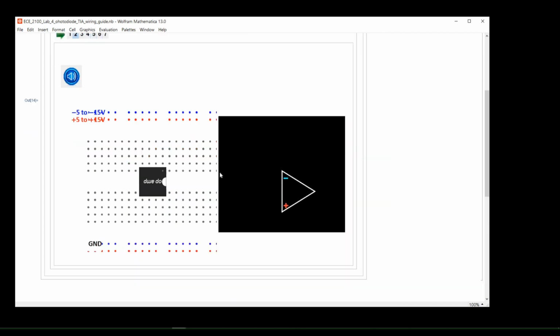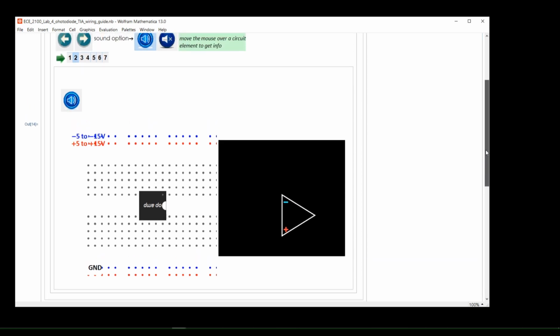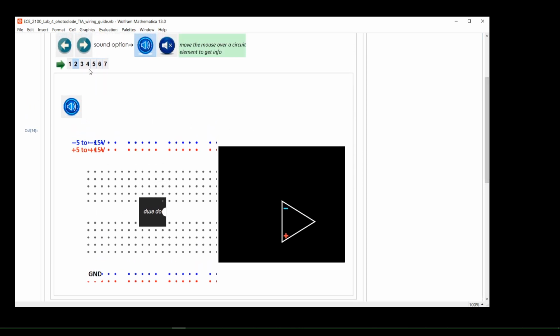In the following, the op-amp is placed upside down. The mouse should be hovered to verify the pin number. If one is not comfortable with this configuration, put the op-amp in the upright position, and put wires accordingly with respect to the pins. Insert the op-amp onto the breadboard by gingerly rocking back and forth, side to side, to align the pins to the holes, and gently push down. Avoid bending the pins. Next, when ready.